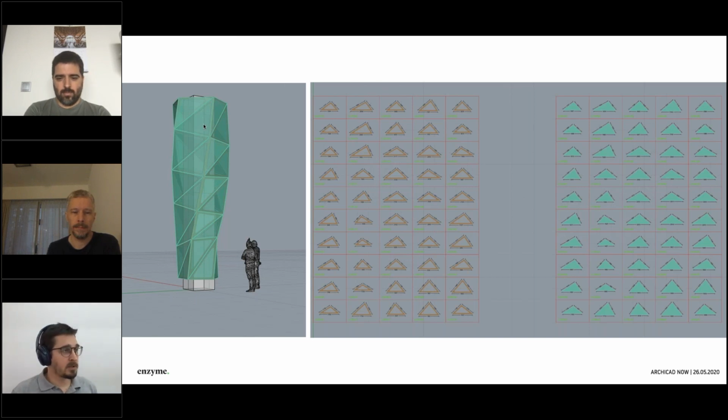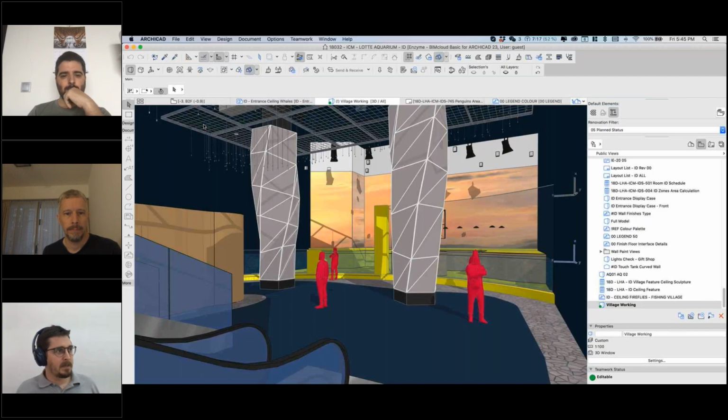By using Grasshopper as well, we could automate the naming of the different pieces and also the dimensioning. So we created all these documents as 2D AutoCAD files, exported in DWG, and then merged them. We merged the columns separately in the ARCHICAD model, so you can see them here within the space, obviously for design coordination, for the creation of elevations and plans, etc.